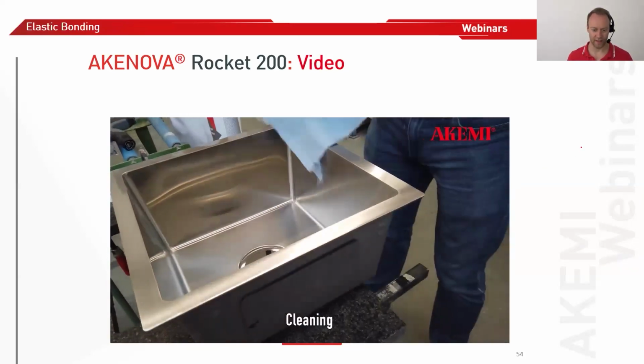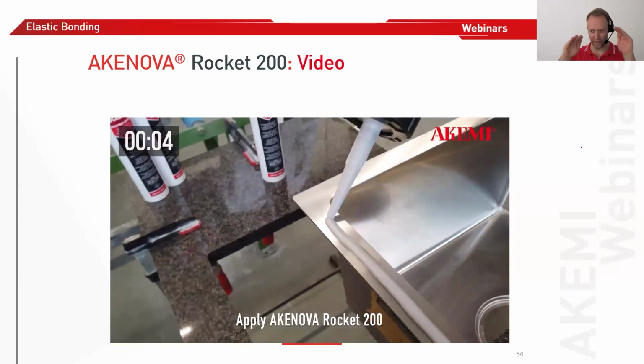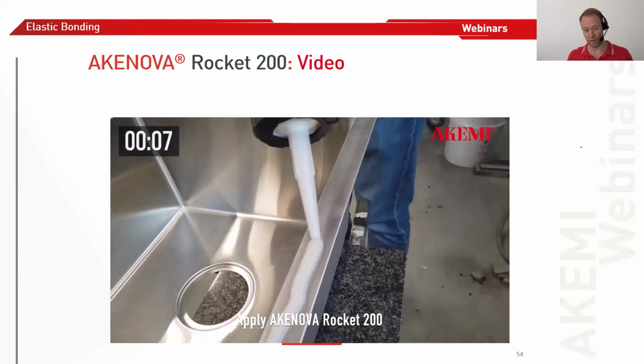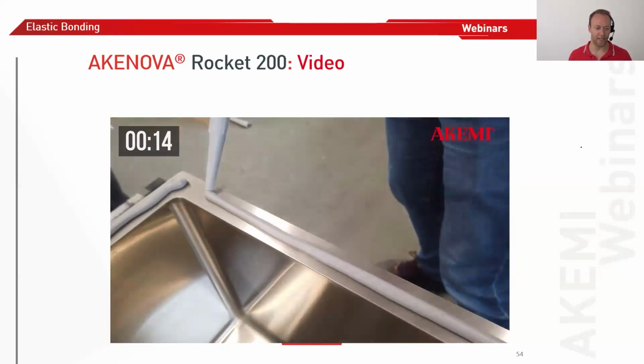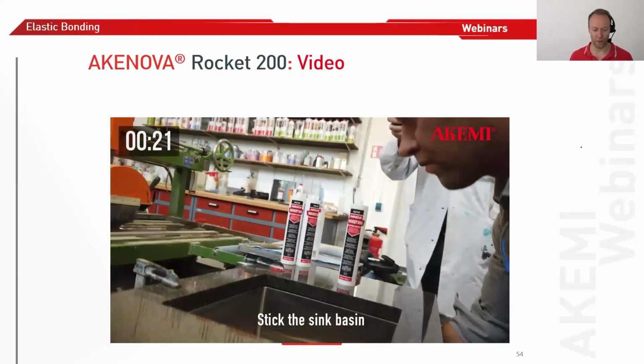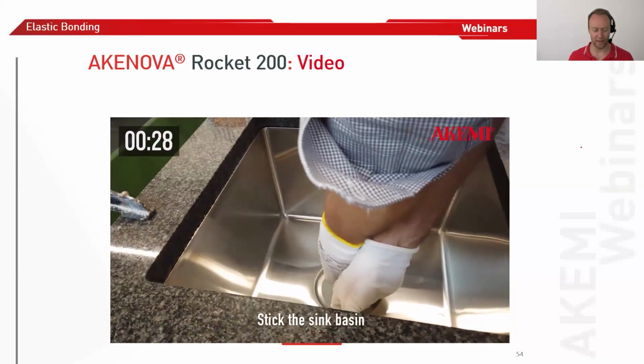Classical stainless steel sink. Of course, clean it first. We don't need any greasy finger tabs there because this will reduce the adhesion. But then you can see no roughening needed directly on this brushed surface. You press it there, it's pressable.